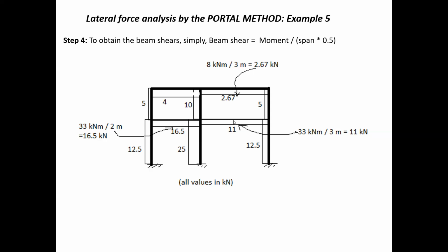So, and you do the same for the other beam. So very simple, just add the moments up, divide by the length, or just use one of the moments and divide by half the length. It's up to you, okay? Any questions on that?